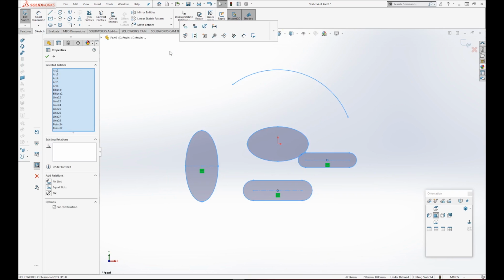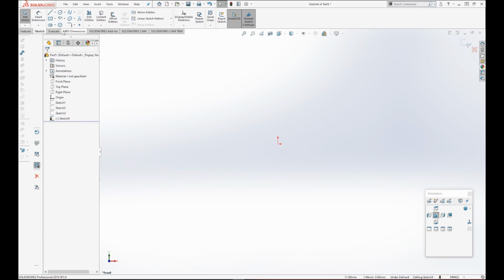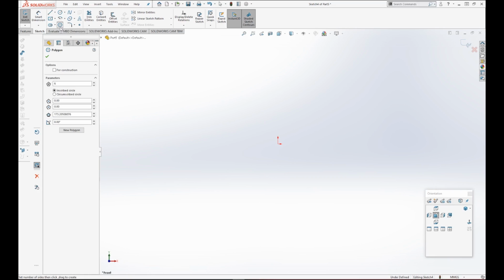This is going to be the polygon tool. Let's select the polygon tool, and down at the bottom it's going to change and show a number 6 right here. That's telling me that there's going to be 6 sides by default. Let's click on the center origin, and you guys can see the preview shown in yellow. I'm going to click right above the origin, and it's going to give me a hexagon. I can change the number of sides by changing this number right here.